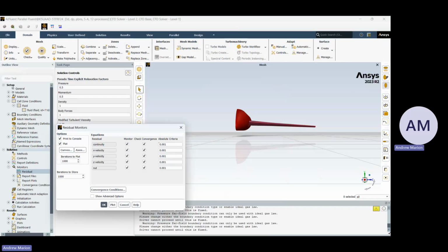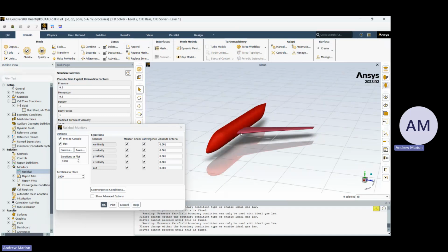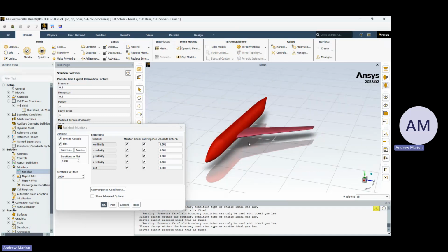Lift force. Lift coefficient, you just select it. Coefficient, wing, leading edge, and trailing edge. Anything involved with the wing. That's just so we capture the full geometry. If you just put the wing on there, it would just be the top and bottom of the wing. It wouldn't include the edges. I guess it would affect it some.